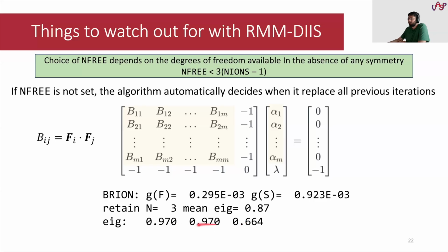And the eigenvalues are basically reported in the std out file. So take a look at these, make sure that they're not super large. Otherwise, you're probably drifting through something where you don't want to go. It's a good heuristic to check whether things are working out as they should.